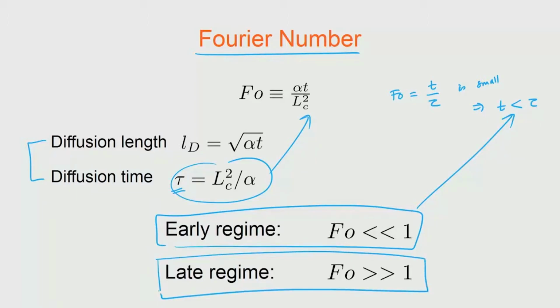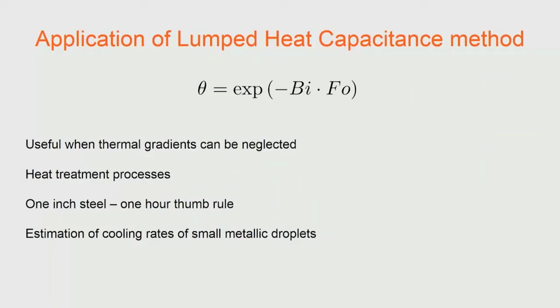So, this quantity which we just now cooked up as a non-dimensional number, the Fourier number, is actually having a meaning. If the number is small, it means that we are in the early stages of the thermal diffusion taking place, and if the number is large, it means we are in the late stage of thermal diffusion taking place. Okay, so, now our solution can be written with the non-dimensional numbers used in the solution expression, and that means that the expression is coming out quite elegant.